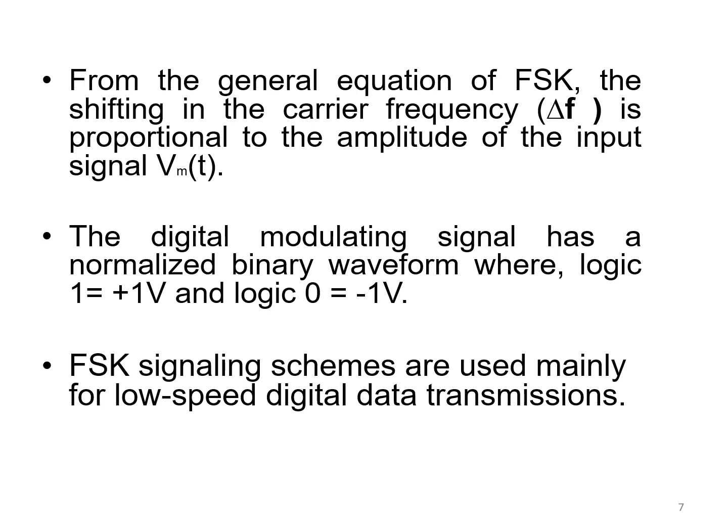From the general mathematical equation of the FSK waveform, the shifting in the carrier frequency is directly proportional to the amplitude of the information signal. Notice that the digital modulating signal has a normalized binary waveform. That means logic 1 is represented by positive 1 volt and logic 0 is represented by negative 1 volt. The FSK technique is mainly used for low-speed data transmission.